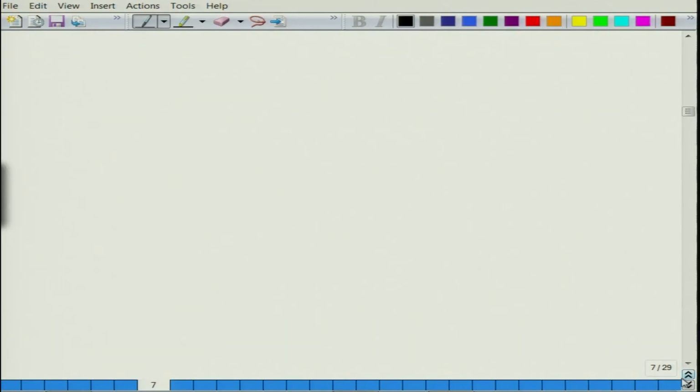So, now let us do the substitution. So, sigma p cube minus I1, which is 13 into sigma p square, minus 115 sigma p plus 138 is equal to 0. So, this is I1, this is I2 and this is I3.